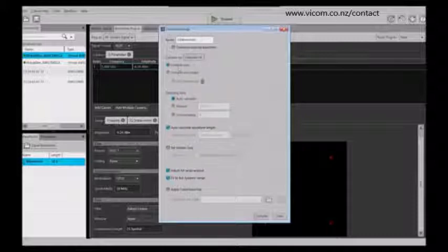You can compile only and load it into the waveform list, or you can compile it and assign it to a waveform. And then if you're connected to an instrument, you can automatically have it play once you've compiled a waveform. You can set the sample rate to auto-calculate depending on the characteristics of the signal that you're creating, or you can manually go in and set the sample rate that you want. Or you can set it as an oversampling feature, such that if you want 6 times oversampling, then it will calculate what the sample rate should be.